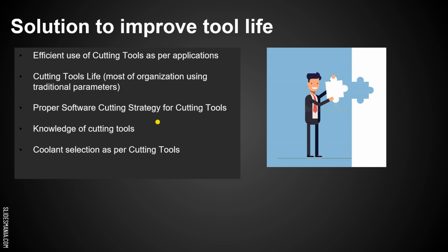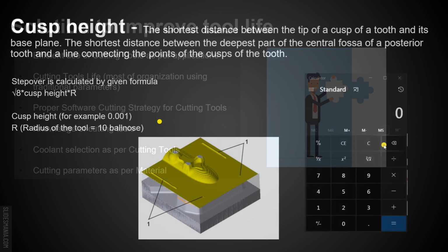In an indexable cutter, I recommend to all of you to use air compressor only, and in finishing areas you can use coolant. Because in finishing, due to the magnetic field, our hot die steel holds on to all the small burrs, so the coolant pressure will remove all the small burrs, and it comes out in better finishing. Cutting parameters as per material.